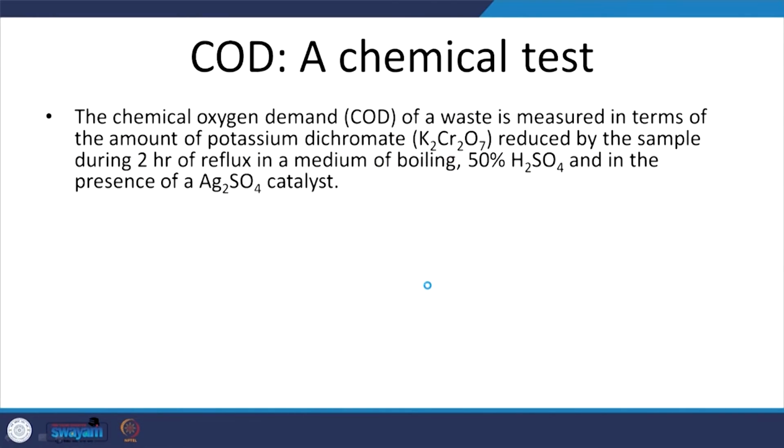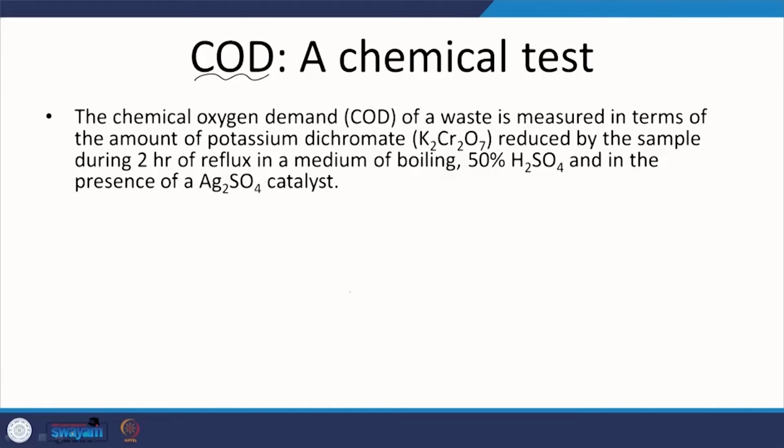Let us move on. As I mentioned, COD is relatively faster and relatively more reproducible, unlike the BOD test, which is slow and, depending on the kind of waste and whoever is doing it, you are going to have issues with respect to reproducibility. COD is not really such an issue, but it is relatively costly, because the ingredients are costly, but one aspect is that the amount of lab space required is pretty much less.